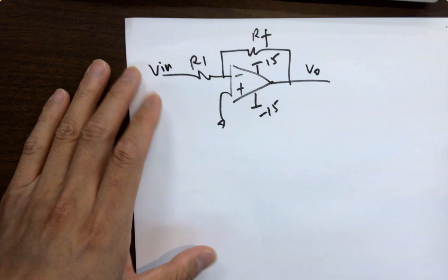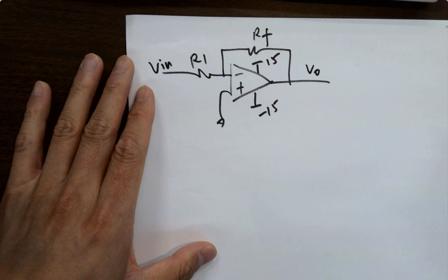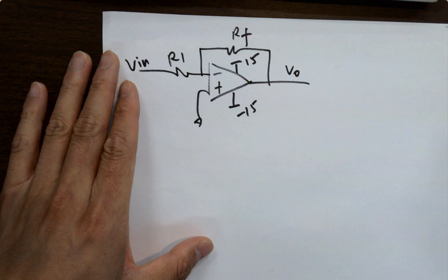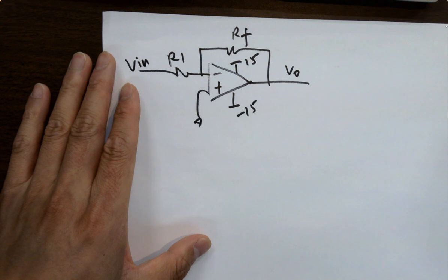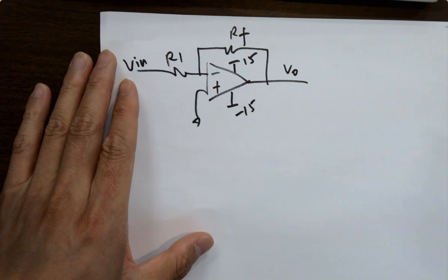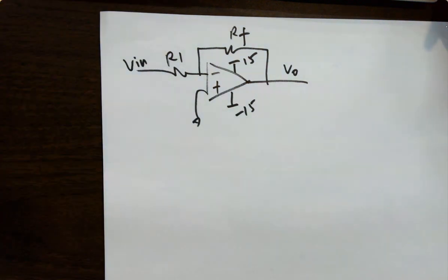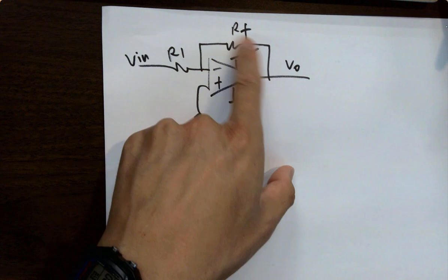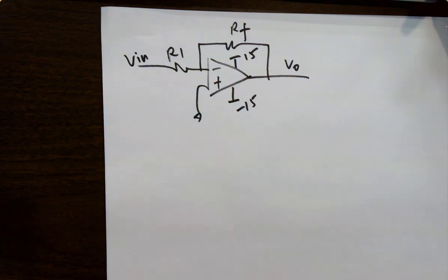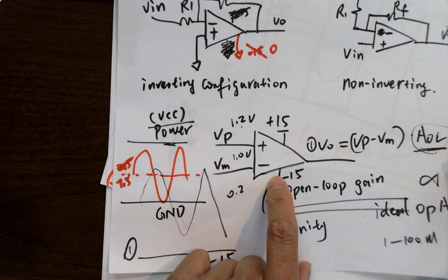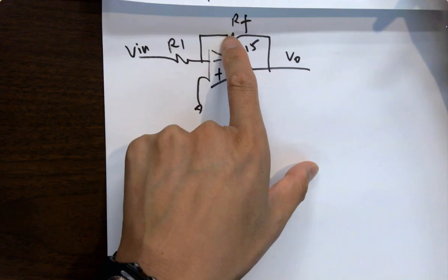What's that? I was just wondering, we discussed how the comparator provides gain. What sort of loop would I want if I just wanted 2 times gain? You cannot, because that's a comparator. If you want a 2 times gain, you have to use the feedback. Yeah, so how would I get that if my motivation is I want to gain 2x on the signal? It has to be this. You cannot use this. It's a comparator. You have to use feedback to achieve that.